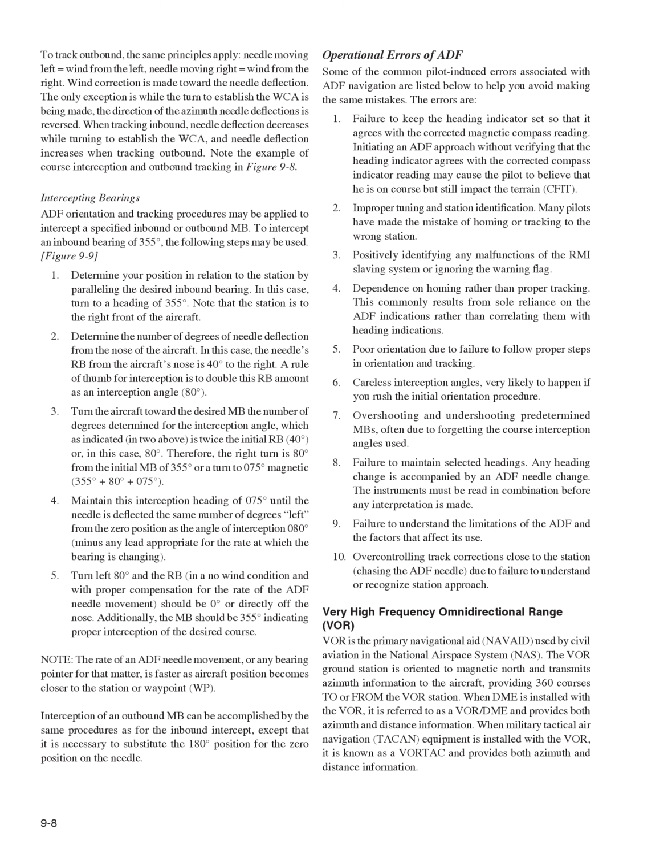Note, the rate of an ADF needle movement, or any bearing pointer for that matter, is faster as aircraft position becomes closer to the station or waypoint, WP. Interception of an outbound MB can be accomplished by the same procedures as for the inbound intercept, except that it is necessary to substitute the 180 degrees position for the 0 position on the needle.